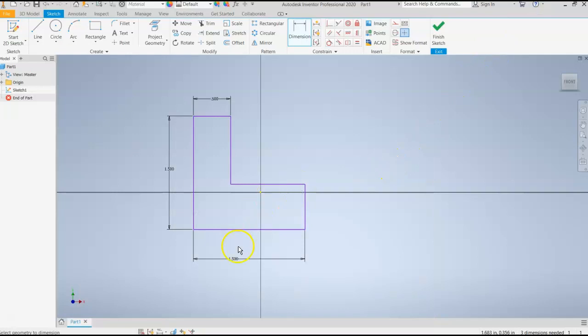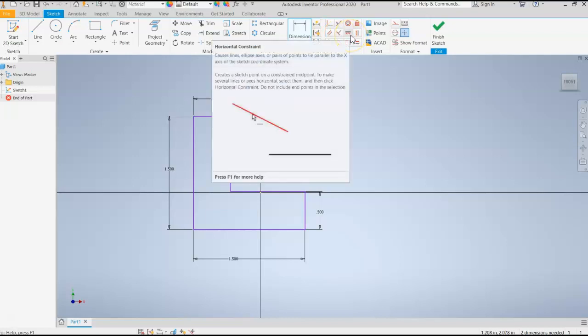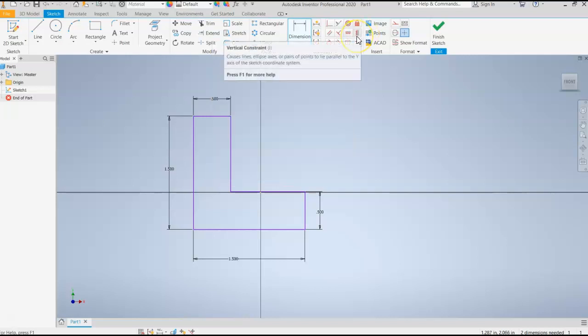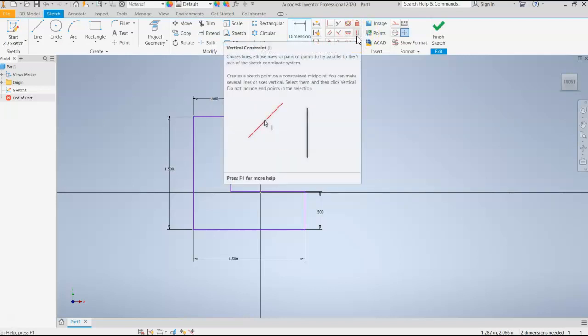the computer kind of does that for you. And so if we go through and finish dimensioning, this is 0.5 here. So this is 0.5 width, 0.5 height, 1.5. So now I have my dimensions correct. I can show these different geometric constraints. There's my equal sign. There's my parallel sign. Up here is my horizontal constraint to make that line horizontal. Here's the vertical constraint to make a line completely vertical.